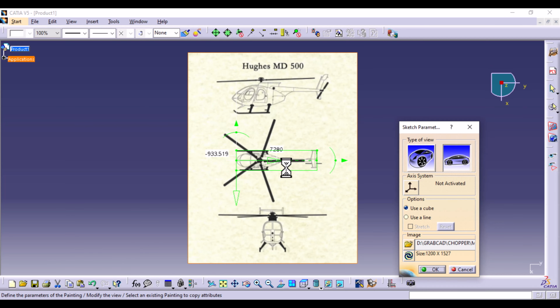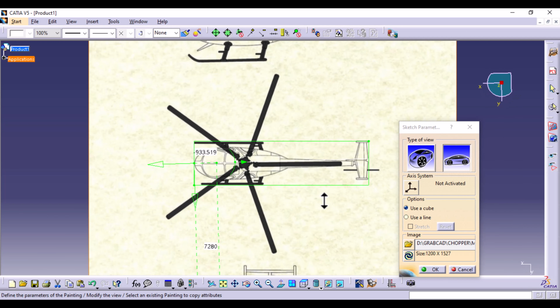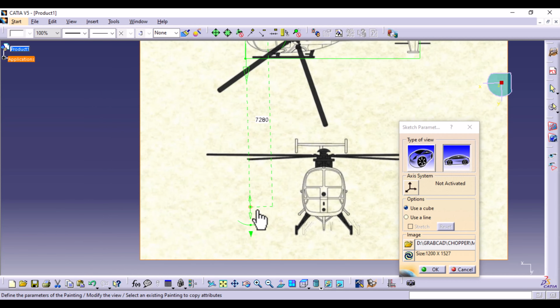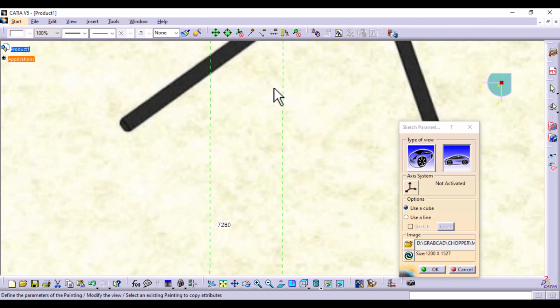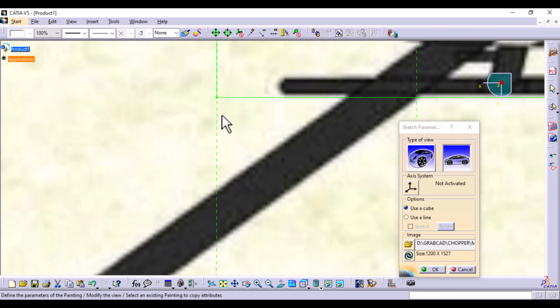So once again, double click on that. And you can use the compass to see where the X direction is. So the X direction is this side. So you're just gonna take this and rotate it towards the X. And you can use this line to guide you where the 90-degree angle is. So basically the dotted line should just go over this corner right here.